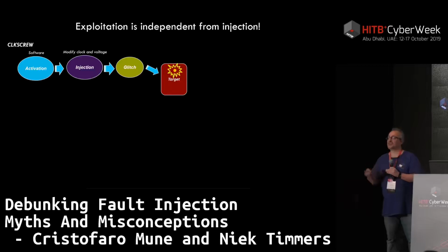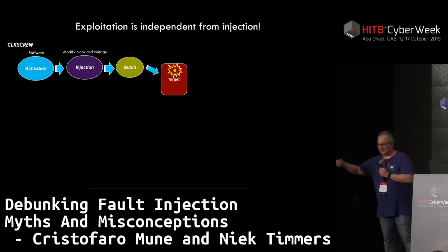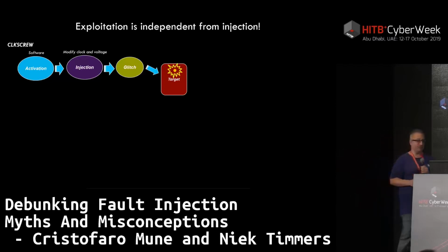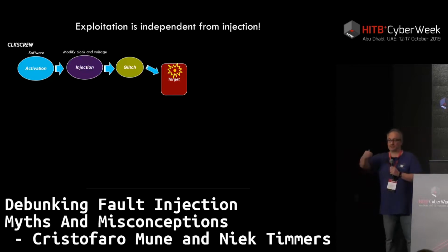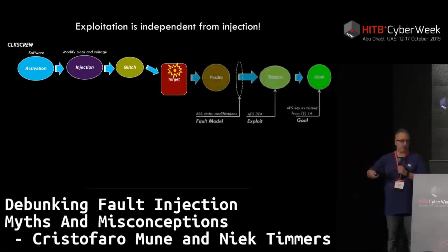But these registers are accessible, and you control the power for each single core. So one core can decide through this register how much power or how much frequency another core will be running at. And this is a very important point in the research, because this allows one core to inject glitches in execution that would cause faults in the execution of another core.